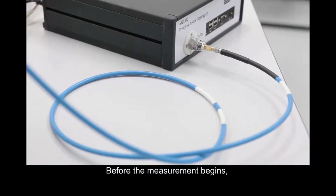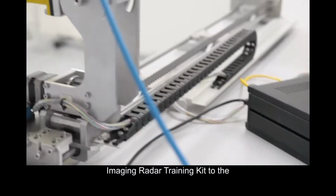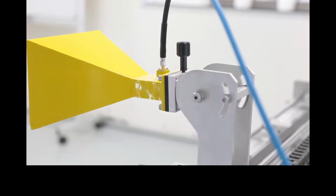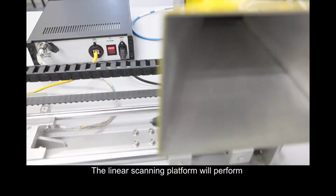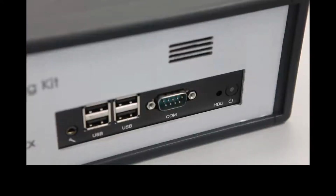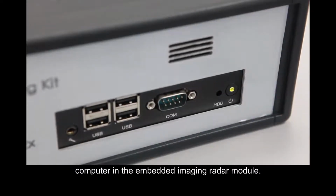Before the measurement begins, connect the SMA connector of the ME1510 imaging radar training kit to the horn antenna via RF coaxial cable. Power on the imaging radar kit. The linear scanning platform will perform an auto-homing sequence as part of its initialization process. Then, boot up the high-speed single-board computer in the embedded imaging radar module.